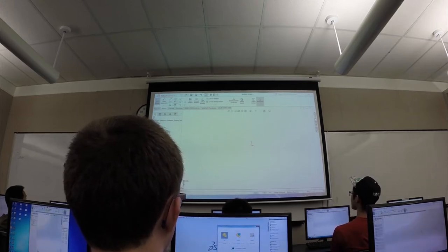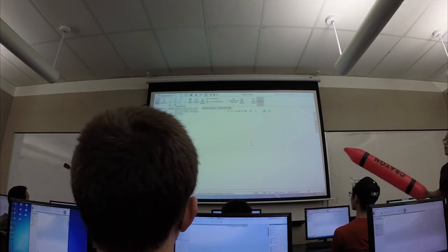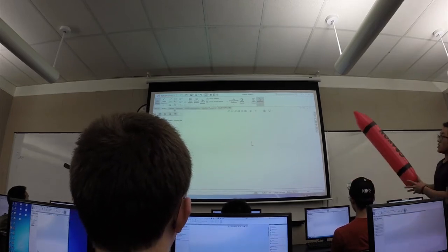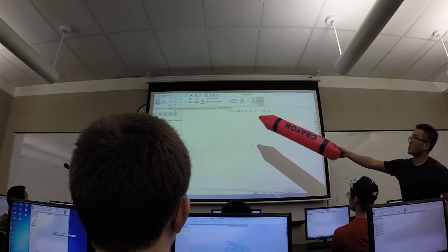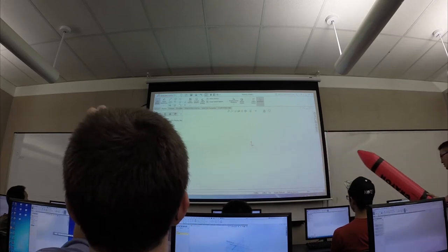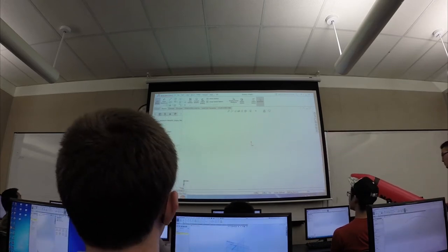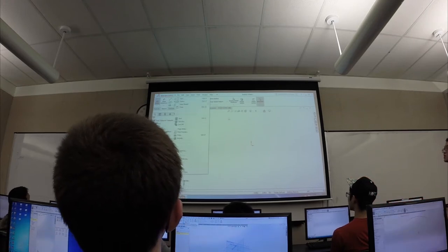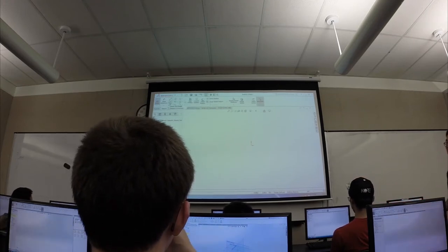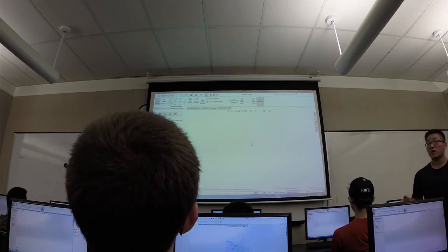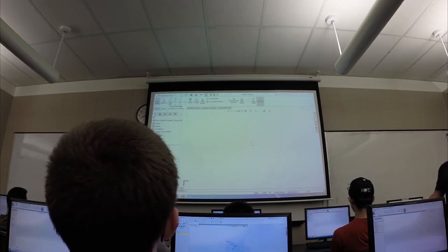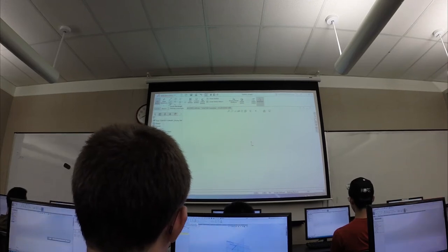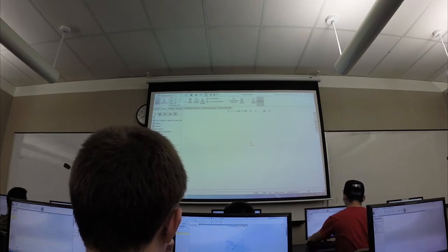So once you have your plane selected, this section right up there, where you see the lines, the circles, that squiggly line, this portion right here, those are your sketch entities. So you can consider each line that you make as an entity of some sort, an object, right? So we'll be starting off with making some lines here.